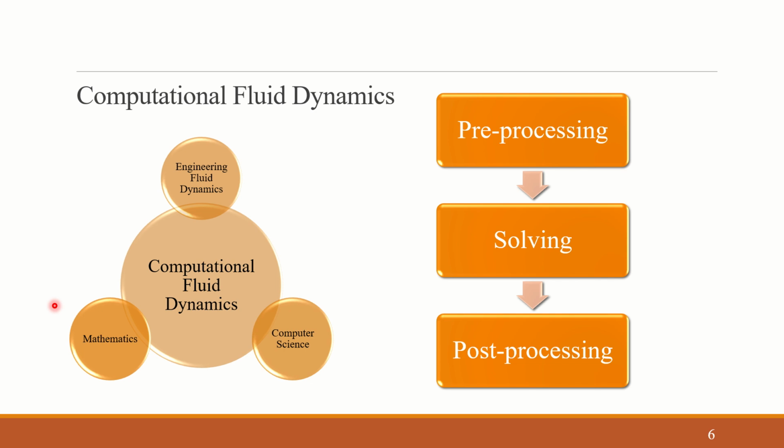For example, to give you a basic idea, what we do in CFD is we solve the conservation of mass and conservation of momentum equations, so that we know how momentum is exchanged and how mass is conserved inside the system. These two equations are simply solved when we are dealing with systems where only fluid is present and it is a cold flow system. There is no external heat transfer taking place.